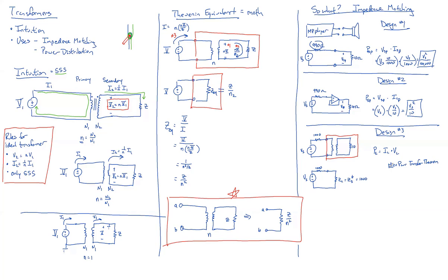I think you might have not been in class for that one. It says that if you've got a source and a Thevenin equivalent impedance of that source, which you can't change, and you can't change the voltage source, and you want to know what load will dissipate the most power, it's equal to the complex conjugate of the source. So that's just another thing to know.